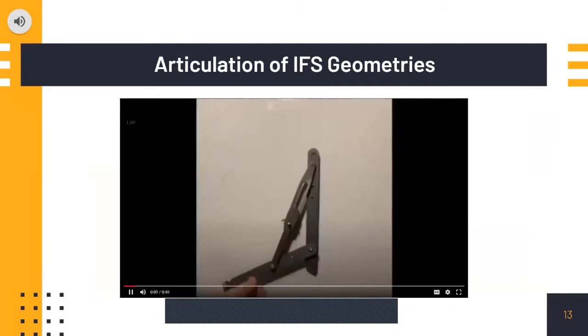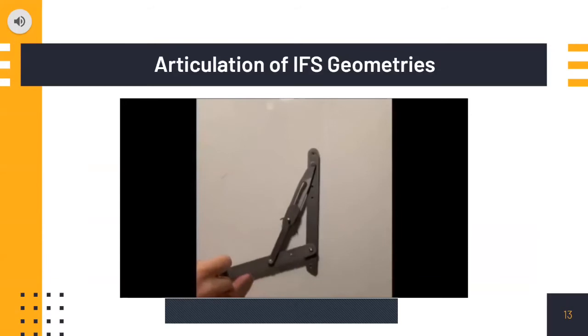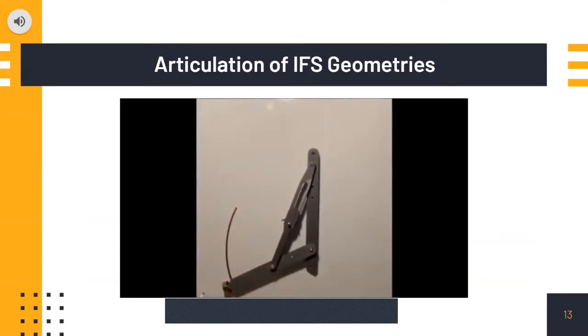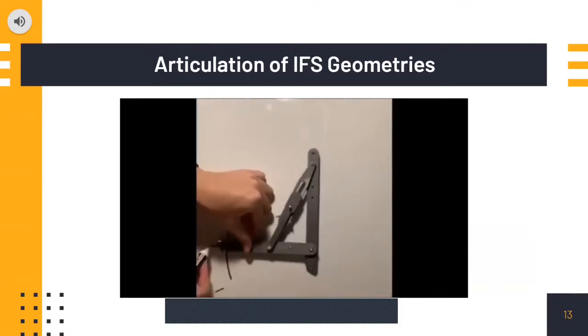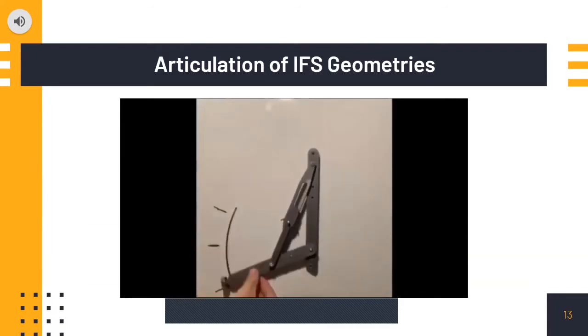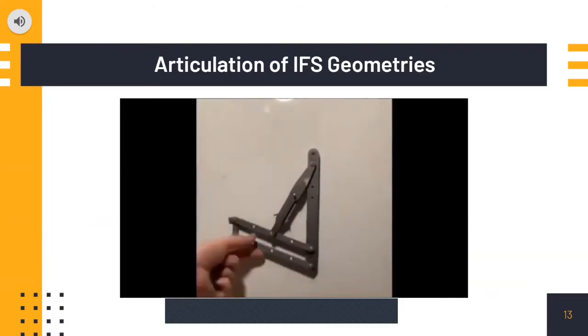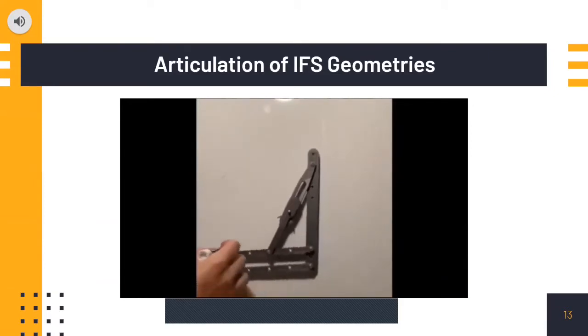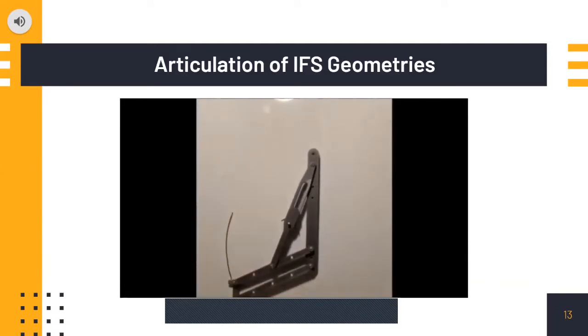Starting with the Freeboard suspension. Notice as I trace the axle's endpoint, it forms an arc. Now notice as I mark the axle's orientation that it is always radial from the center of rotation. Next, we look at the parallel bar system. Notice how the axle follows the same arc as before. But now, when marking the axle orientation, it is always horizontal.